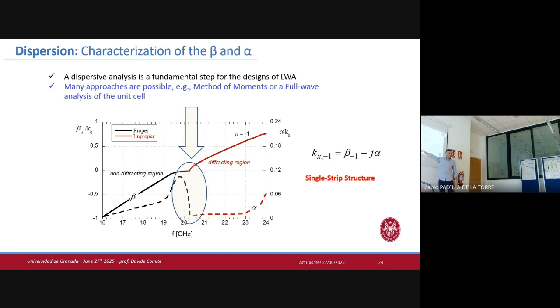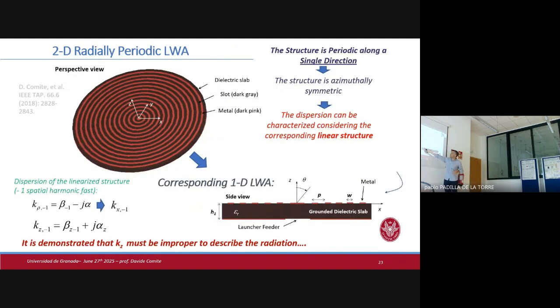So the behavior that you were seeing before in the rectangular waveguide loaded with irises is here just for one frequency. So it means that where beta is equal to 0, you cannot leak power. It's incredible. You want to radiate at the broadside because essentially when you radiate at the broadside, it means that you are illuminating these slots here with the same phase. So leaky-wave theory is just a tool. There are a lot of people in the world that can design this antenna using leaky-wave or using array theory, because you are illuminating slots here. So that's the point.